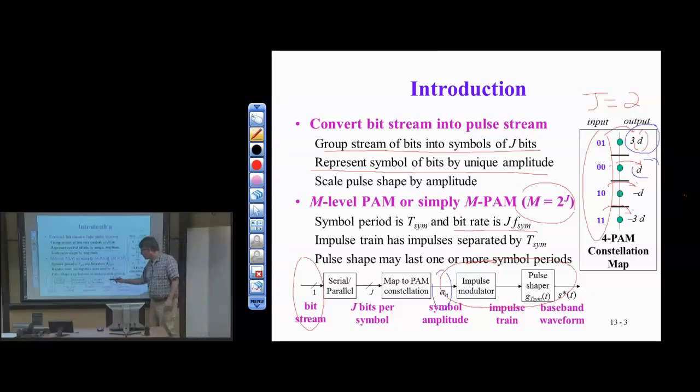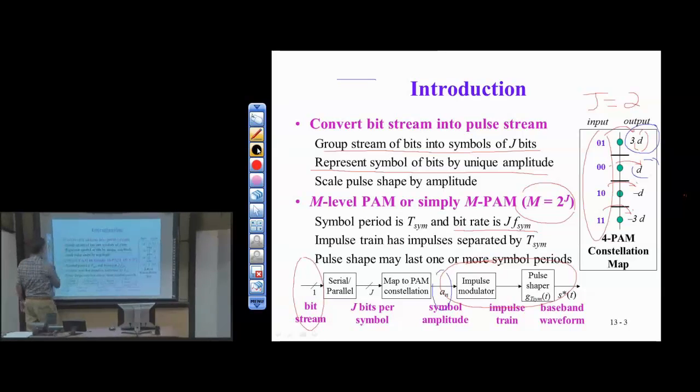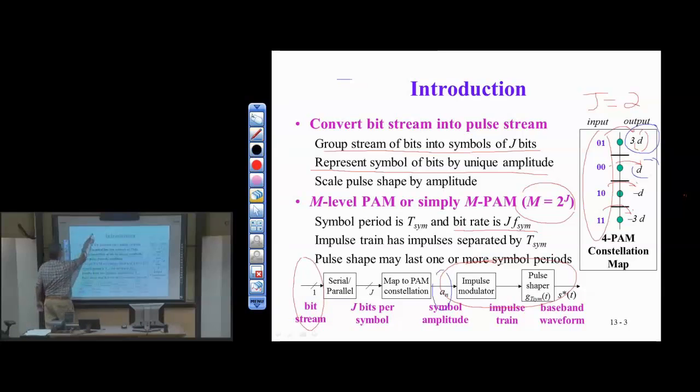So we're going to filter this impulse modulator output, which has all frequencies in it and harmonics of the symbol rate. We're going to low-pass filter that, so band limit as best we can. Can't exactly band limit, but at least low-pass filter this output of the impulse modulator. Okay, so what does this impulse modulator output look like? It's going to be a pulse train. Again, this is theory, it's kind of hard to build an impulse train in practice. We can do it with really narrow rectangular pulses, about the best we can do.